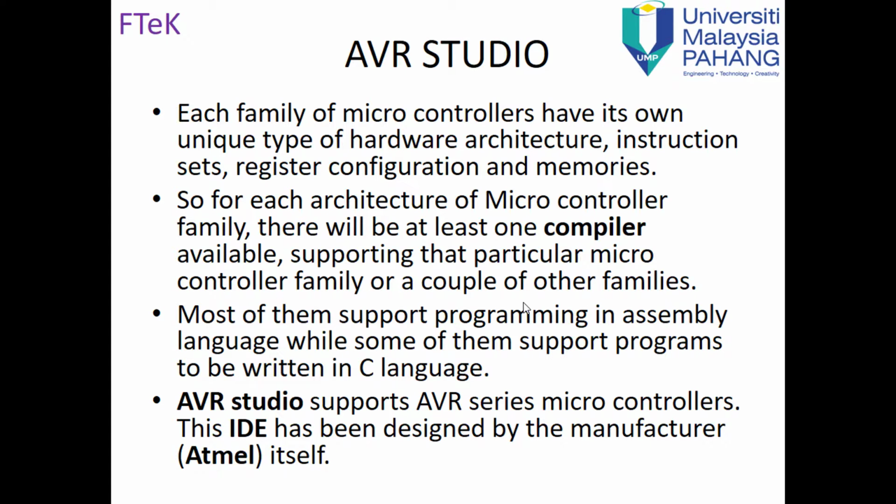Now we will start speaking about AVR Studio, how to use it to write a simple program and how to compile it and prepare the file which includes the machine language program. AVR Studio is related to the AVR family. Other microcontrollers have other software, because each family of microcontrollers has its own unique type of hardware architecture, instruction sets, register configuration, and memories. So when we study the ISA, we study all of this.